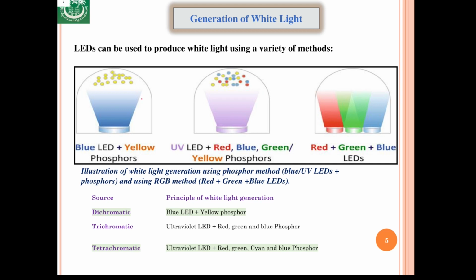So any LED cannot be directly used as a source of white light, which is so important for illumination purposes. This issue can be solved by combining light of three colors, for example red, green, and blue, from three different LEDs. But different LEDs have different luminous efficiencies, therefore this solution becomes quite impractical.